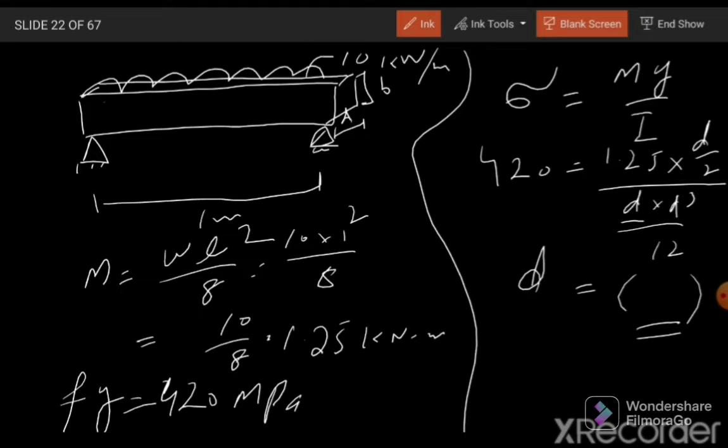So this is the way of designing structure and it is termed as the direct method. So from the applied loads and conditions, we have calculated the internal gross forces, and because of those internal forces, we will compare them with the material strength, and as a result we will get the sectional properties or proportioning of the section.